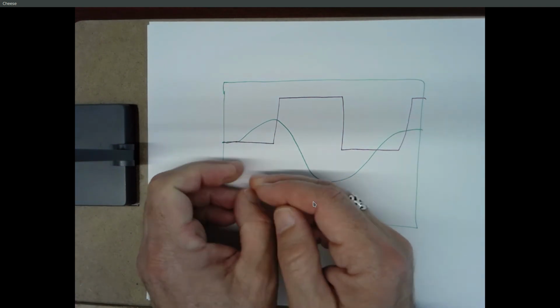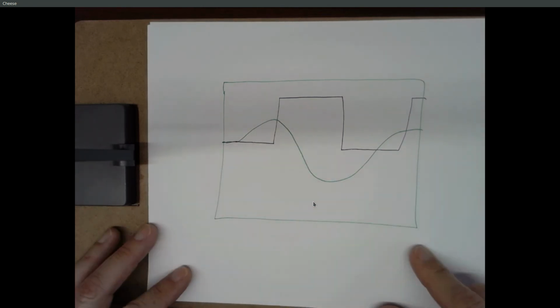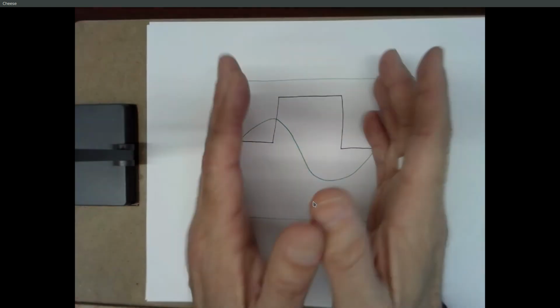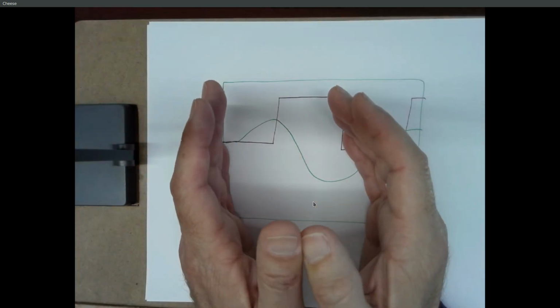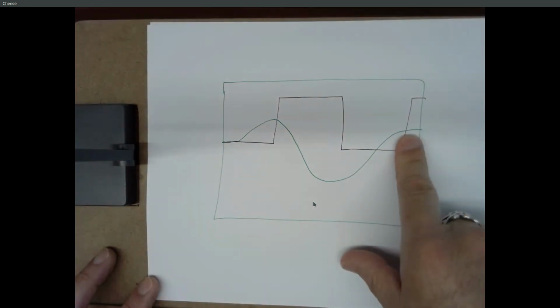So what are the variables? Well, how quickly do you move from one side to the other? If you move very slowly, you're going to get a bunch of up and downs right next to each other. Your waveform is going to look really squished up. If you move really fast, by the time you go from one end to the other, you might have raised your arm only that much. You're going to get a very slow change. Okay? So you can change how much this waveform gets spread out by adjusting how quickly this moves across. So we can basically adjust the frequency that we're looking at. So if we have a high frequency, we can change how quickly we sweep, and we can still see the waveform, so it looks like that.